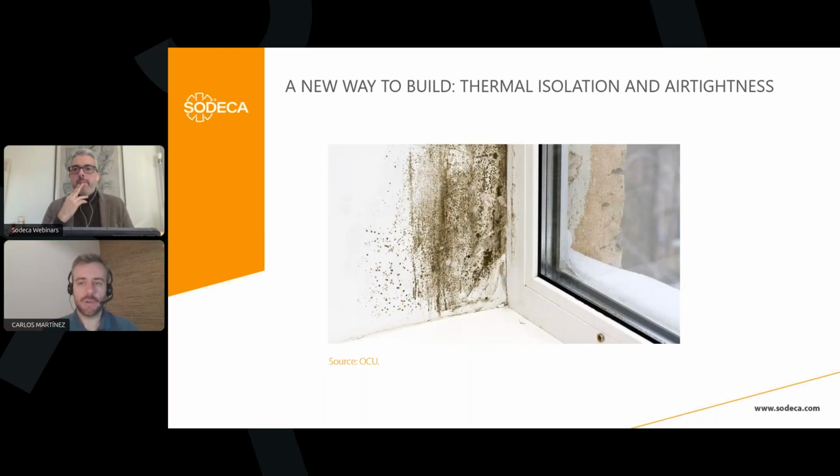Why? Because it's becoming quite common for buildings that undergo these improvements to experience condensation-related moisture. Okay, as you can see in the image, these problems typically appear near the windows. Okay, near the points that are colder than the surroundings. So this occurs basically because mechanical ventilation has not been reinforced or taken into account accordingly.